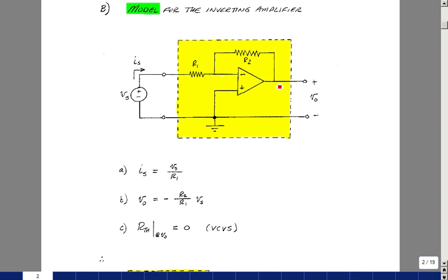Well, between these two terminals, here and here, back through the op-amp, there's actually a voltage-controlled voltage source, so really infinite gain times a 0 voltage across here. Well, it's kind of a strange element. It's still a voltage source, and so any load you put here won't change the value of the voltage. But back in the 201 notes, I actually derived an expression for the output resistance looking back in a little bit more formally. This is, I call, more of a seat of the pants argument, where I'm just going to use some simple principles to argue why something's true.